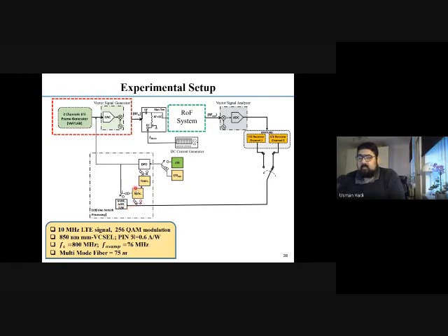Once you synchronize it, you train the system, the training block that you saw in the previous slide. You have the digital pre-distortion output. You see the reference so that you can time synchronize it with the reference block that we have. And once you perform this DPD, you provide your output coefficients of the DPD to your signal generator with the help of this LTE frame generator that is implemented in MATLAB.